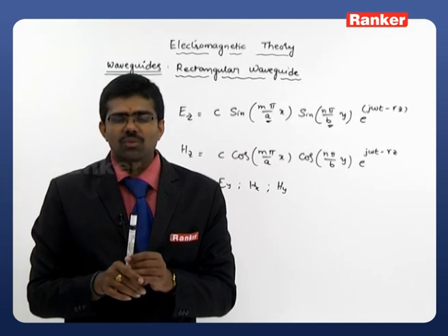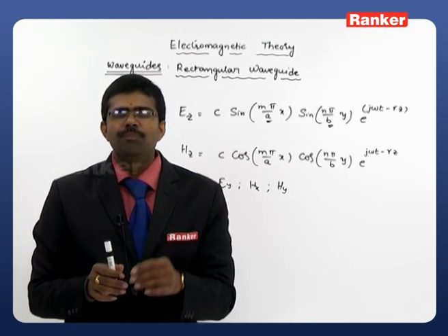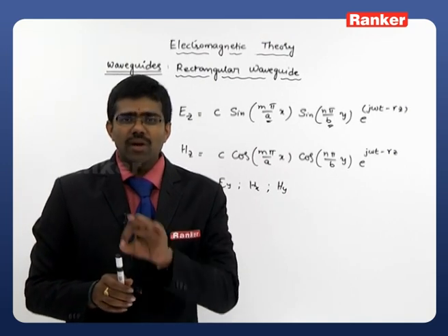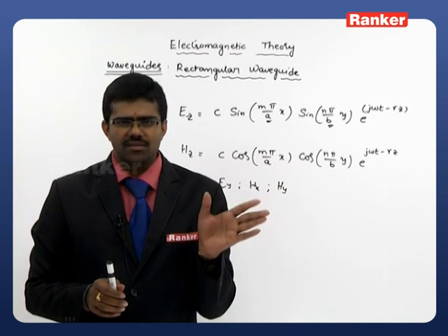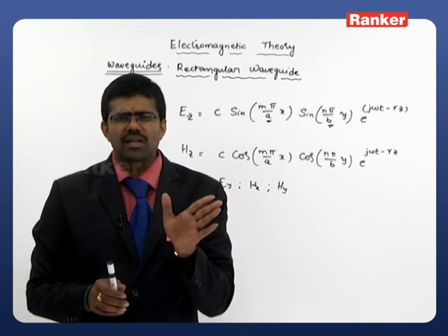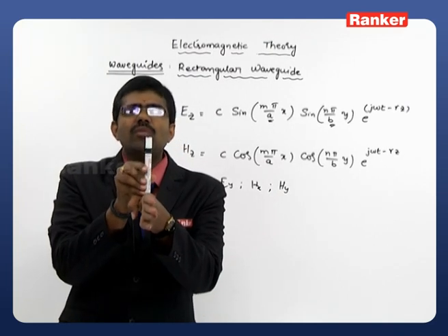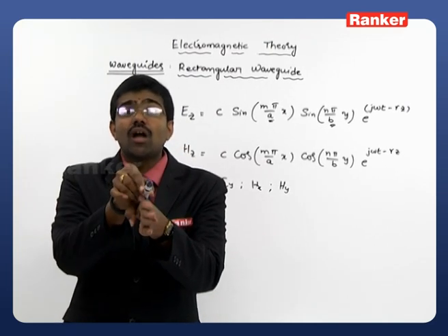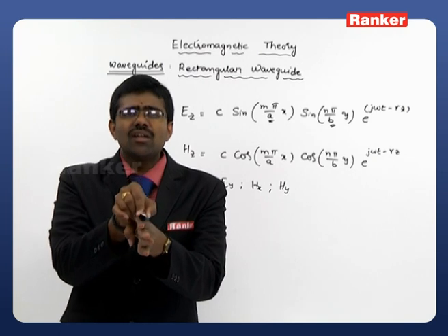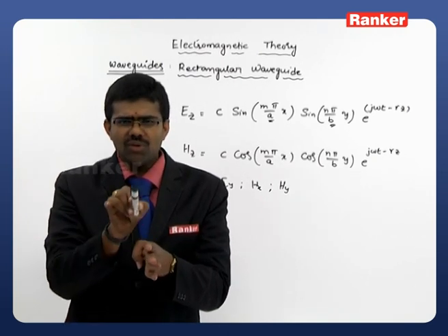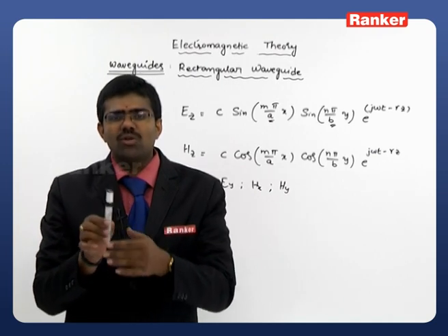Transverse magnetic wave is similar to that one. The magnetic field is transverse to the direction of wave propagation. Blindly remember, perpendicular. Let us take this as the direction of wave propagation, then the magnetic field may be like this, like this, but not like this. The magnetic field along the direction of wave propagation is 0. That's what we have. Now, the transverse electromagnetic wave.